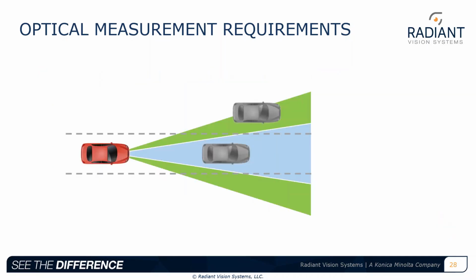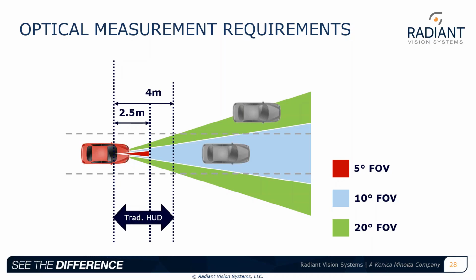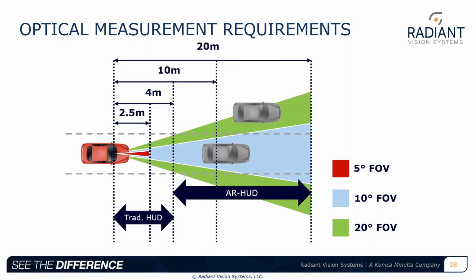So the key differences in head-up display measurements come with meeting the new demands of image distance, resolution, and field. When we look at traditional head-up displays, we see that they have a limited projection depth, which I've talked about already, usually within a few meters, but could be up to 4 meters as an example. These images don't respond to the exterior environment and basically are static in regards to the information being updated. If we look at augmented reality systems, on the other hand, these are responsive and interact with generally most objects on the exterior of the vehicle, and there's constant change in the information being presented, and that information is changing over a much larger field of view.